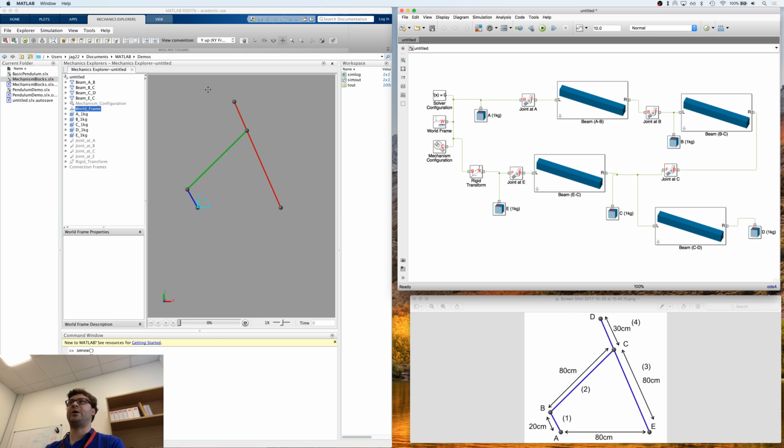So now we're all pretty much set up. We just need to run the simulation and see if it rotates. So we do that. Now it's all the masses, and there we go. So we've got no torque, it's just acting on gravity. And as you can see, it's just racing back and forth, back and forth. And because we haven't got any friction in the system, it's just going to have this continual perpetual motion. There's no actual loss of energy in the system.